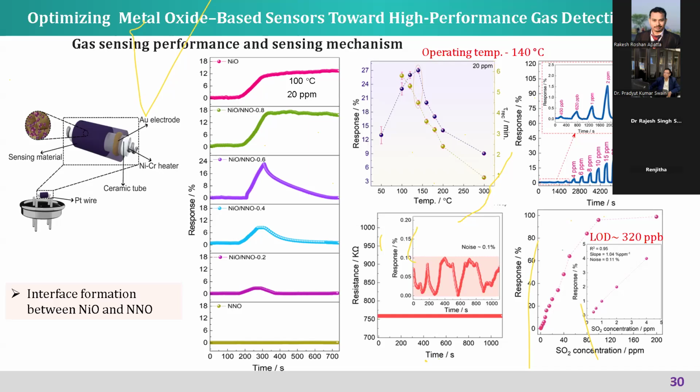But when you have a collection of sensors, we have to have a standard humidity sensor and nullify this effect. That's how one has to do it, by using a program. Otherwise, in the sensor, if there is humidity, accordingly your response will be changing. It cannot be avoided. At room temperature, you cannot avoid the humidity effect.